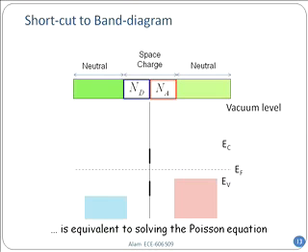The first thing, when you have a blank sheet of paper, step one is to draw a horizontal straight line, and that's the Fermi level. Don't have to draw anything else. First, a straight line through your page. That is the Fermi level, because you know in equilibrium, Fermi level must be flat. So that's number one. Just follow these 4 rules. You'll never be wrong for any device that will come in your life.